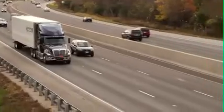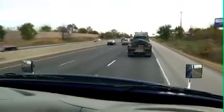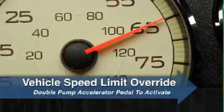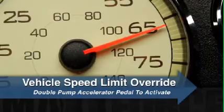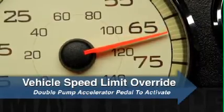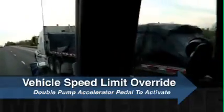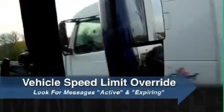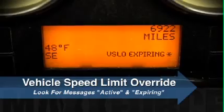There are times when you may need to override the vehicle speed limiter, such as a passing situation. If enabled, you can activate the Vehicle Speed Limit Override, or VSLO, by double pumping the accelerator pedal. Push the pedal to full throttle, release, and push to full throttle again. You'll see a text message, active, to indicate that the override is engaged, and a message, expiring, when the vehicle speed override is about to expire.